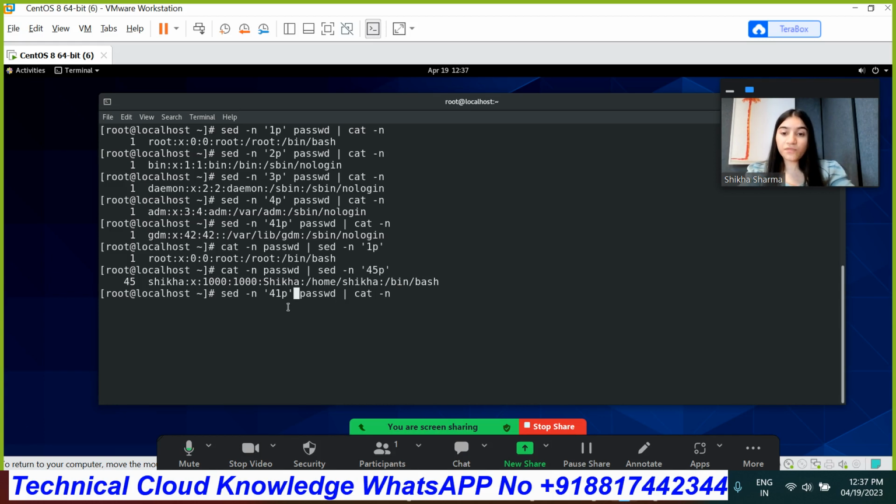Here you need to just define one. Suppose I want the first line as well as the second line together. Right here, first line along with semicolon and then second line. Basically here we are going to use two punctuation marks, semicolon as well as comma. The semicolon is referring to both: I want this as well as this. And the comma is referring to ranges: I want that content to that much level. So that's why we use semicolon and comma. Be clear with both of them.